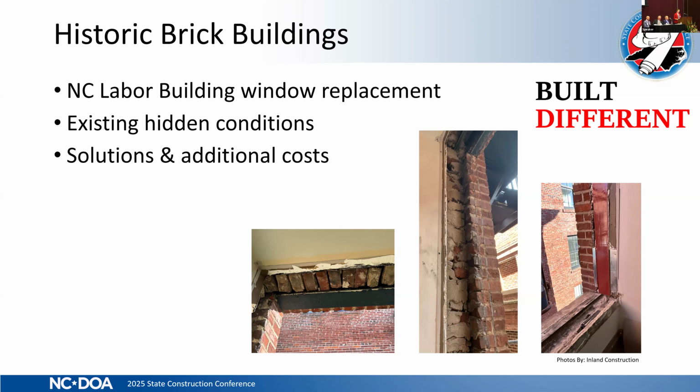Interior sills are left as void spaces as these materials were removed. In some locations, though, the sills are completely solid brick and are actually perfectly fine. Jambs are also left as void spaces until you get back to the broken brick pieces that are held together by brittle mortar. This combination of broken brick and brittle mortar led to not having anything solid to attach new windows to.